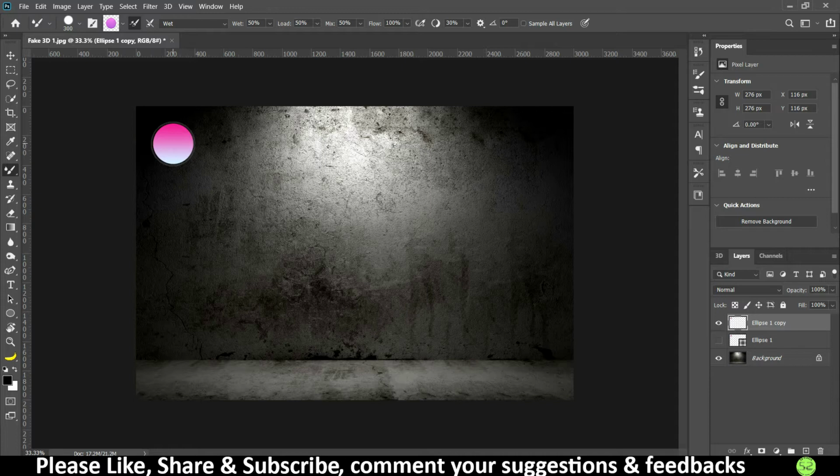As you can see, I have made the brush size similar to the size of the shape. Now I'm going to hold the Alt key, and it is going to sample the colors from the circle. From this circle, I'm going to give a left click and it is going to get selected. Now I can reduce the brush size according to my needs. Let's say I want to reduce the brush size over here to a size of 100.